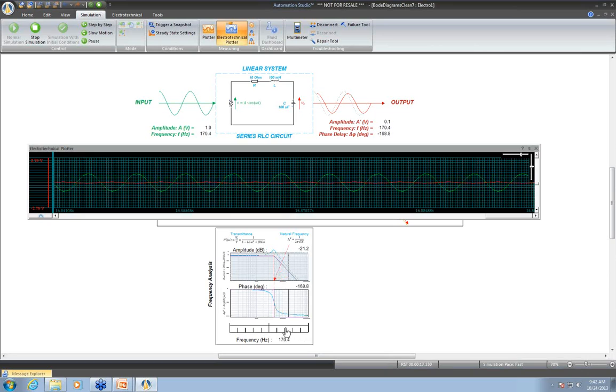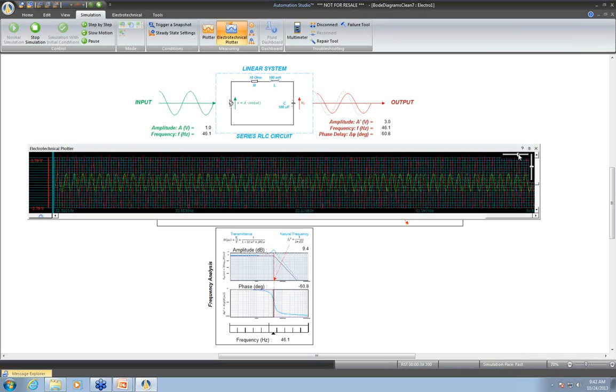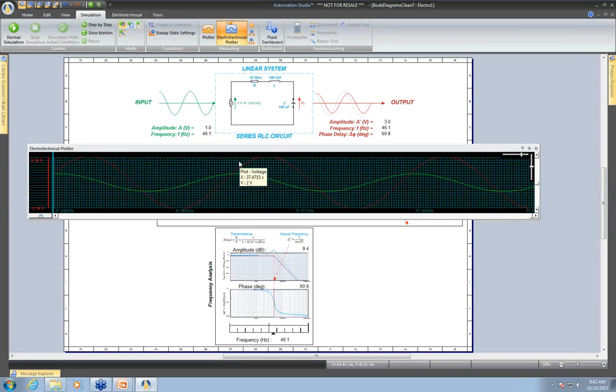So if I go below 200 hertz, you can see here the curve is much more stable and much smoother. This is because theoretically with a fast simulation you can go up to 200 hertz frequency. So if I go below those values, you can see here it's even better values and much smoother curves. You can look at it as well. So this is the latest features that we have added using this new simulator options.